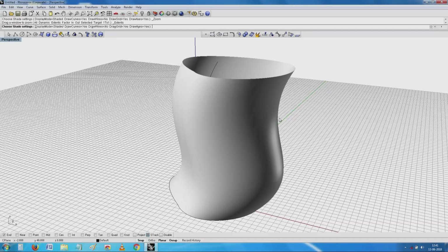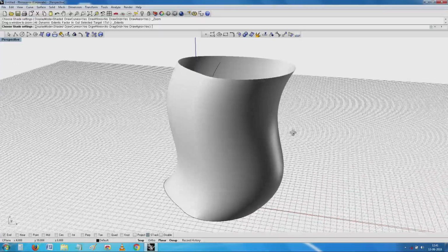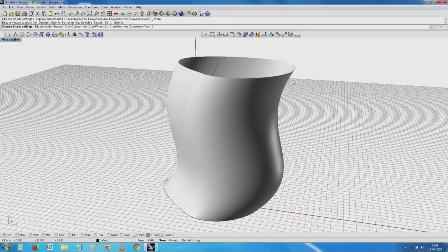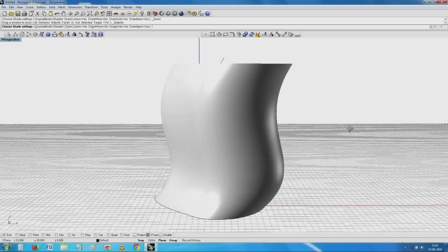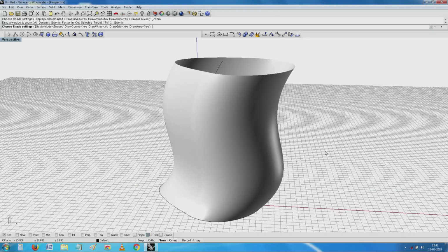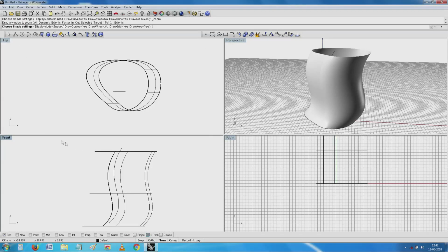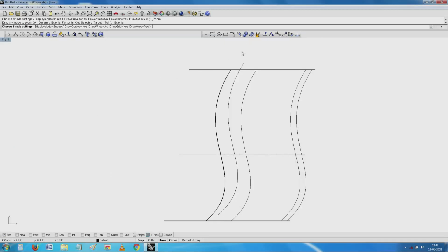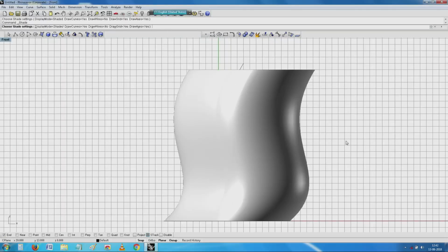One of the first things is, how do you now orient it for printing? In principle there is no problem. However, if you are trying to make shell components like this, the disadvantage is that making it thin is a problem. So you end up with a definite thickness of at least say 1.5 or 2 millimeters and a huge amount of support material. Our problem is the support material. Do you go ahead and spend so much effort and time on this is our issue to the support problem.